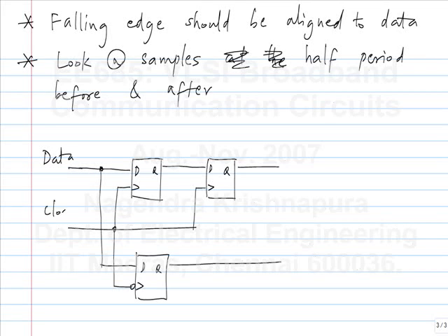This is the data and this is the clock. Now, we usually call these samples A, T and B. T stands for the transition sample, and A and B are the data samples. When the clock and data recovery circuit works properly and everything is in alignment, T will correspond to the transition sample. And which is earlier, which is later? A is the older data than B, right?